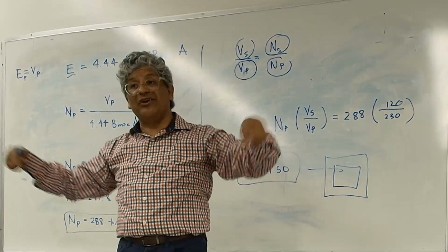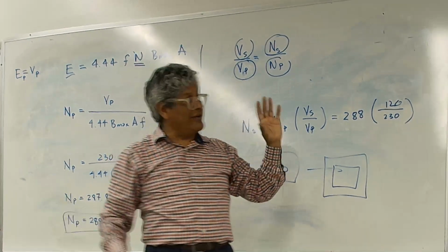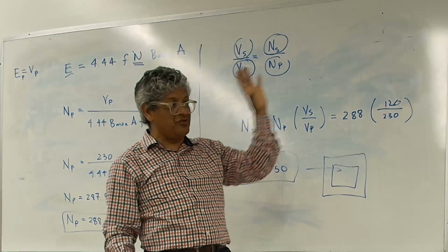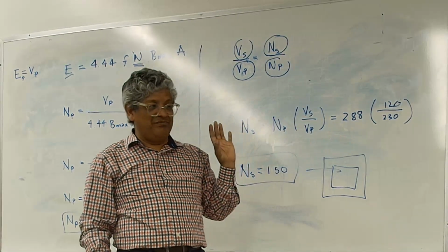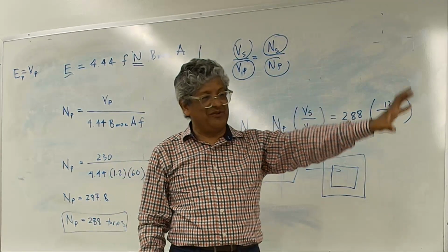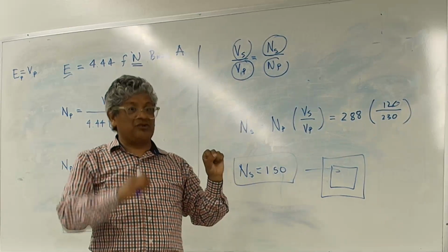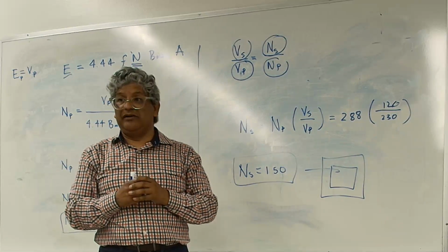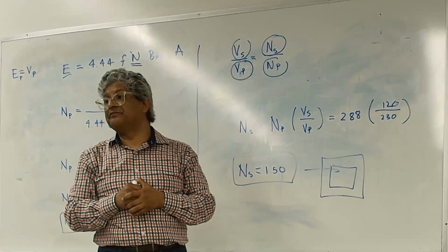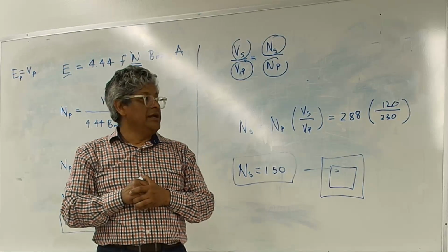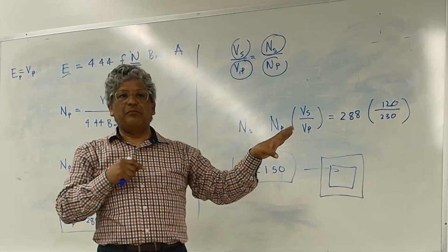But when it comes to current, you transfer the same amount of energy from one side to the other. Say you're getting 99.9% on the other side. As you lower the voltage, you increase the current, so you need a thicker wire. It's proportional, because the power is fixed. I'll come back to this.